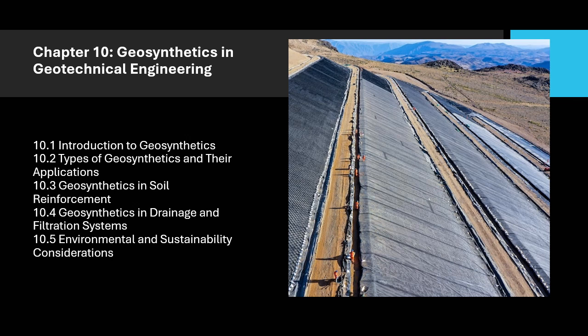10.3.4 Benefits of using geosynthetics in soil reinforcement. 1. Improve soil strength. Geosynthetics improve the tensile strength, shear resistance, and stability of soils, reducing the risk of failure under loading. 2. Cost-effectiveness. Geosynthetics are often more cost-effective than traditional reinforcement methods, such as deep foundations or soil stabilization techniques.